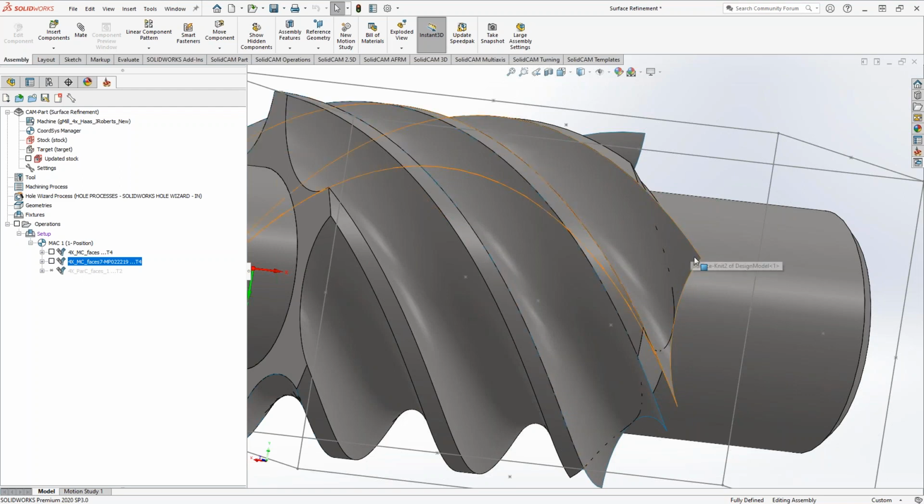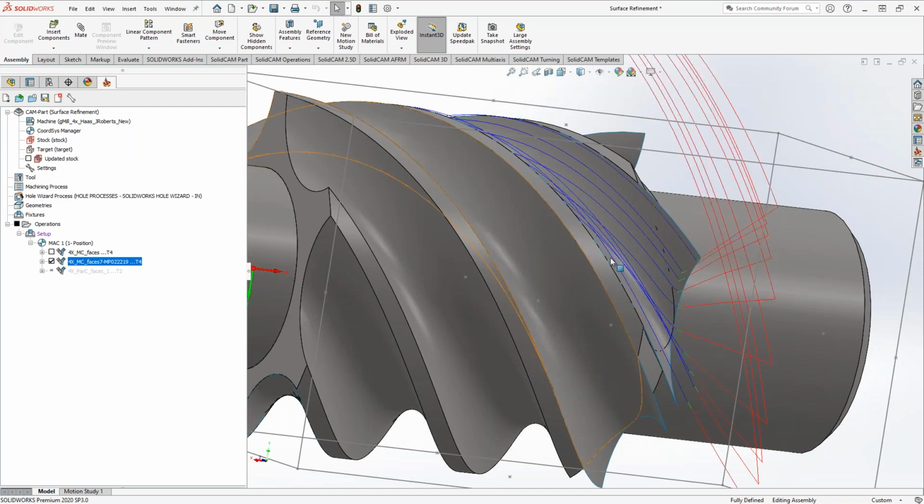whereas if we do this nice sharp corner here, we've got nice smooth splines we can use, and in this case, it actually gives us a little bit of a better connection between the passes, because if you remember, with 5-axis and HSS, essentially what you have is slices, and if the distances between the slices are large enough, it will retract to the clearance plane. If you get something like this, the distances are not that much, and you get a nice smoothness between the slices. So not only is this making it a little easier to program, but it makes the toolpath a lot smoother as well. Kind of like that.